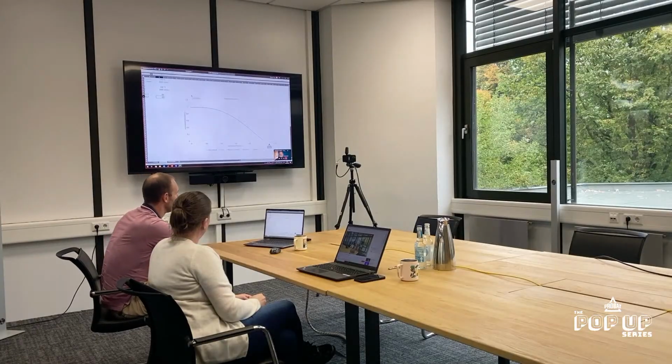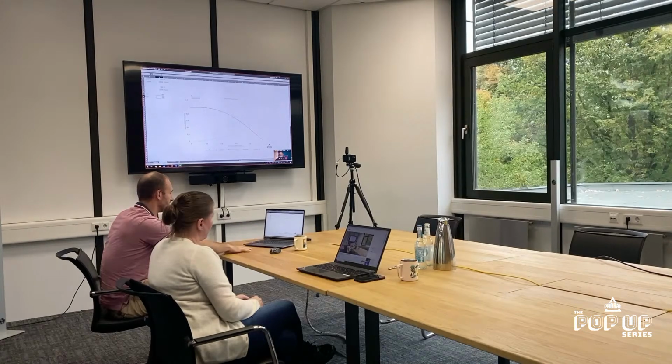Well, some technical issues. Maybe then I talk just in general about it. There's airflow which goes through your roaster, and it's going to be different depending on the type of roaster which you have, because your fan is going to be different and your flaps are going to be set to different values. So if you have two roasters and you put them side by side, it might be the same, but it doesn't have to be. And another problem which we have is the thermocouples.